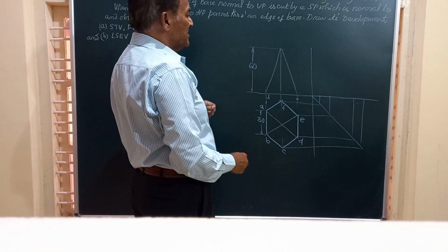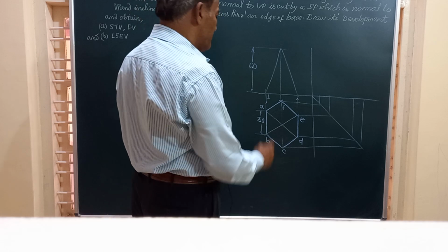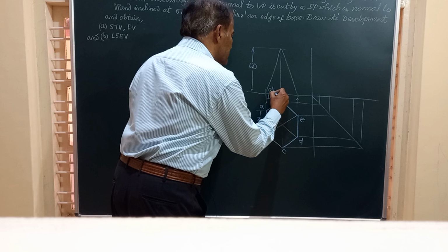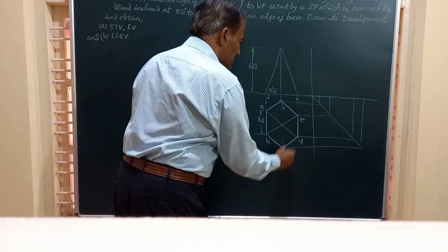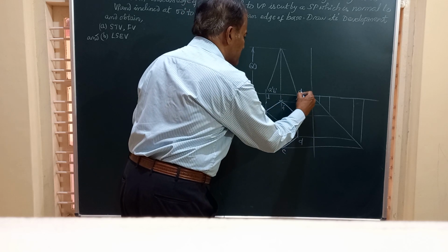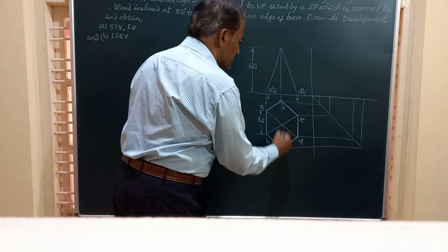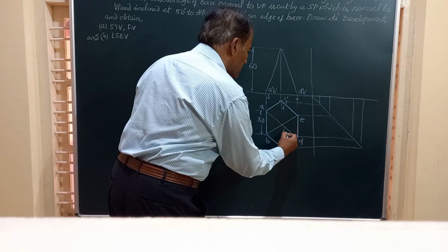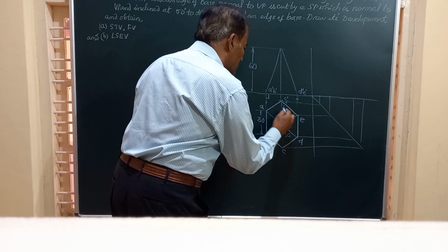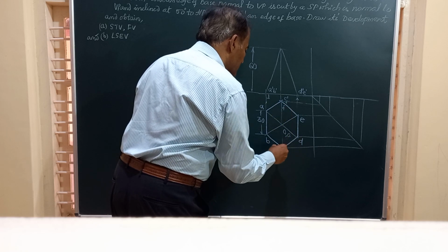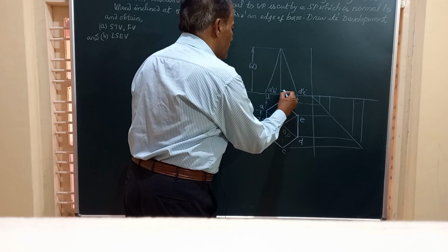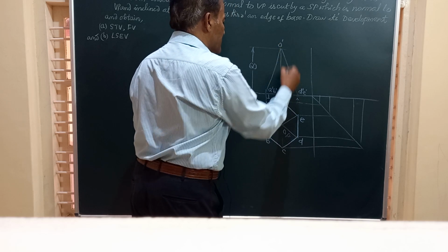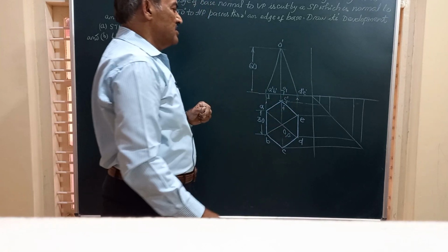And friends, let's see how it is cut by the section plane. Before that, let me transfer these points. A dash, B dash, this is D dash, E dash. Center is C dash, F dash. This is O comma O1, where O is the vertex of the solid and O1 is the center of the base. So we'll call it O dash and O1 dash.